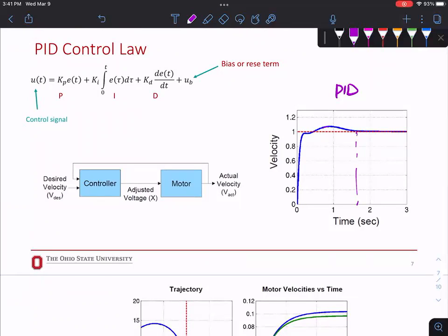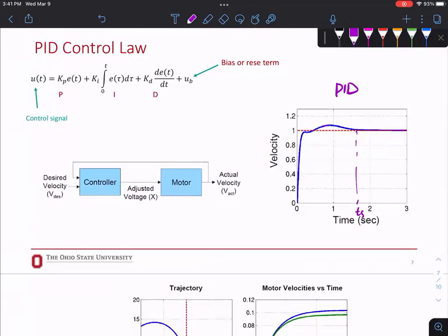So you didn't have to push back the settling time, right? This is TRS. This is also important, because if TRS is supposed to be fast, your motor has to be fast and it can break, so it has to be a stronger motor, more expensive. This is $50, this is $500.